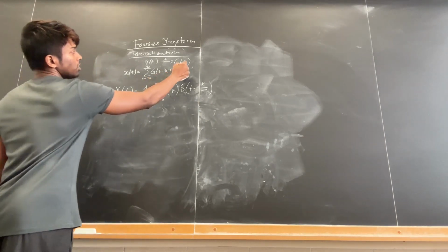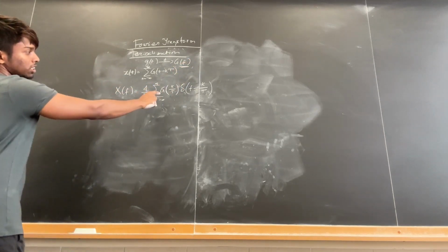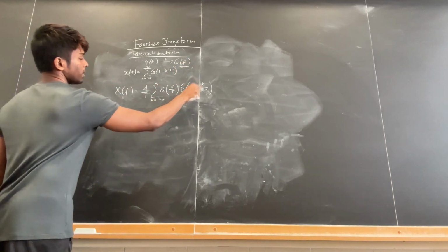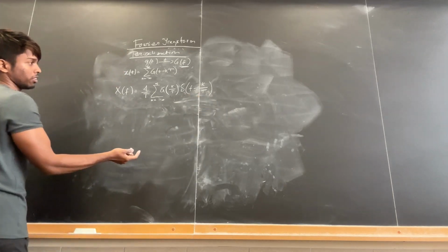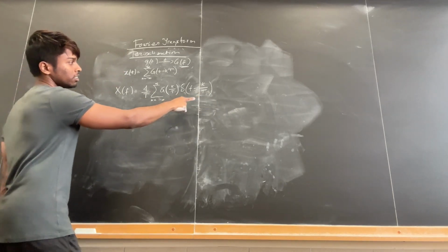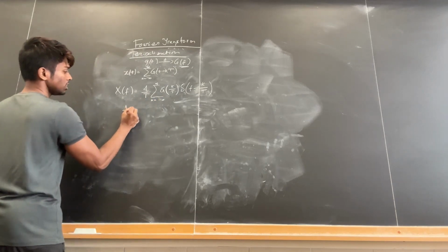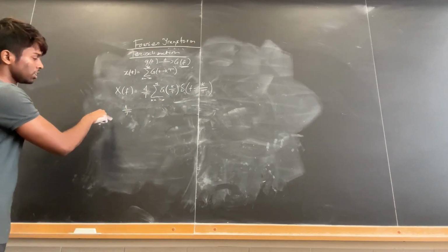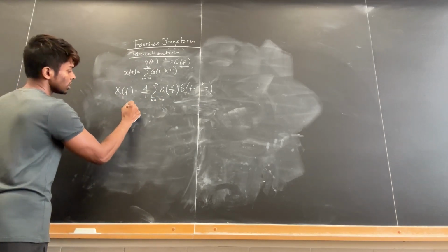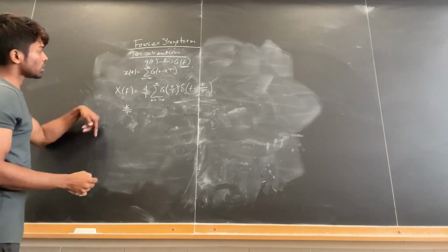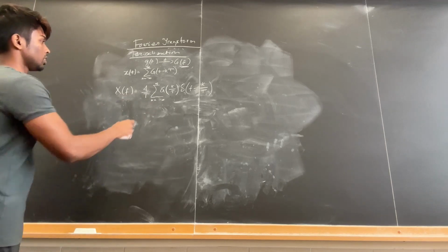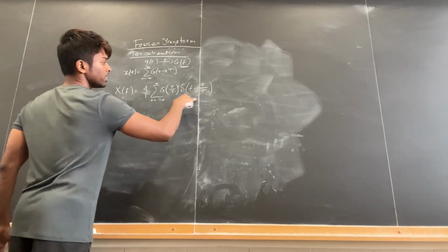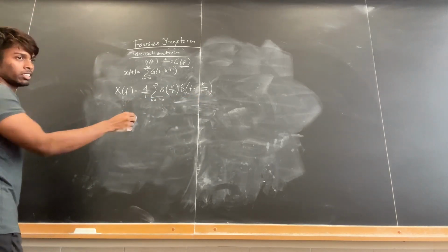Initially the Fourier transform was just G(f), but what is G(k by T) delta(f minus k by T)? This delta(f minus k by T) is actually an impulse train, which is centered at the harmonic frequency. So 1 by T is the fundamental frequency, and integer multiples of the fundamental frequency are the harmonic frequencies. So the periodic signal is x(t) with harmonic frequencies k by T. So the delta(f minus k by T) is the impulse function centered at the harmonic frequency.